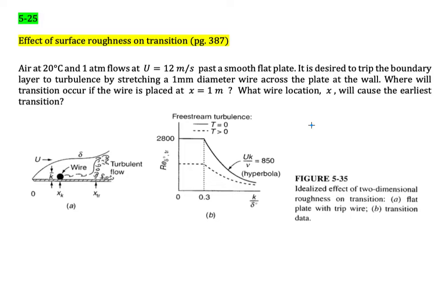And then sometimes we create our own surface roughness. It is also known as artificial surface roughness. Sometimes people call it a vortex generator. They will have dimples, for example on a golf ball, and sometimes they will put disturbances, any kind of rectangular block and so on, on the surface to trigger the turbulent flow.